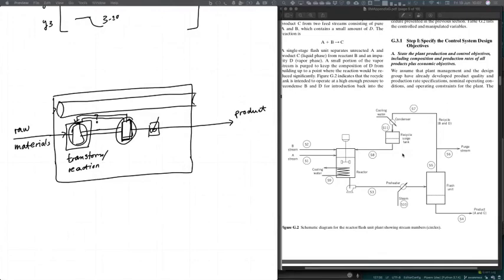And the answer is that we have some kind of target operating condition, right? So let's say that's a reactor that operates at a particular temperature and pressure, right? And we've done our Aspen simulation and we figured out that the absolute best place to operate is over there. That's where the conversion is maximized, or that's where this plant is designed to operate. The problem is that these raw materials, these streams typically look like this, right? So there's no raw material that is perfectly pure, or even if that raw material was like that, the ambient conditions change and so on.